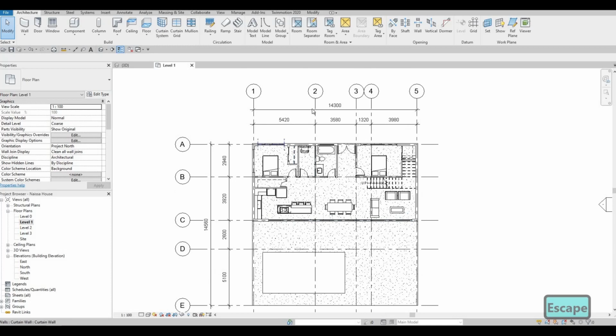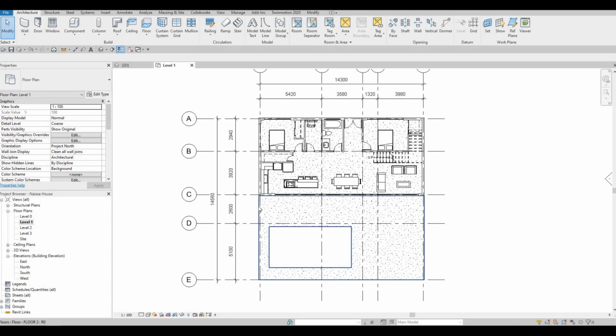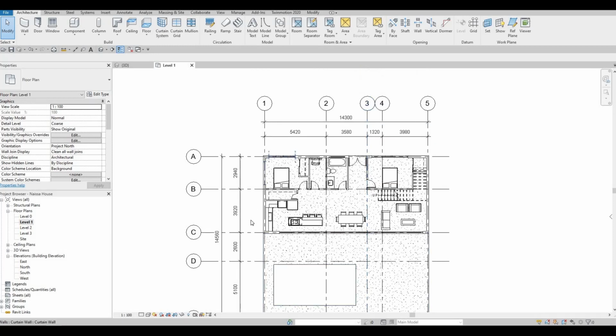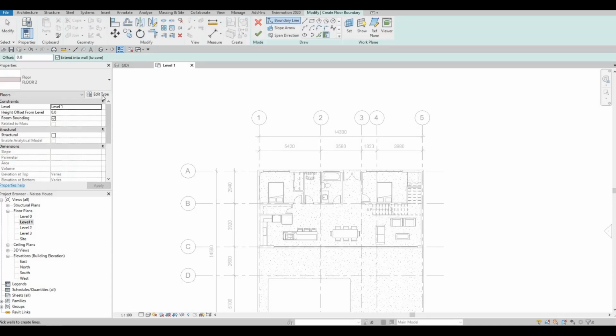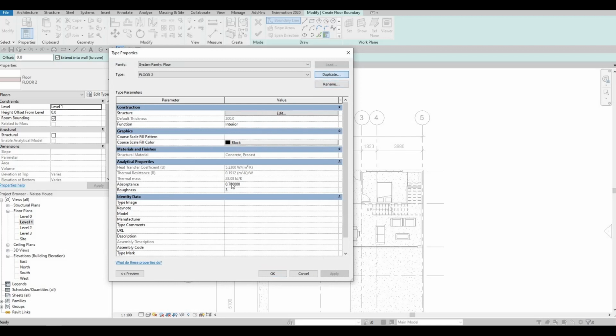And then we are also gonna create the outside here. I'm thinking if we should extend it on the side. So maybe later I'm gonna just extend it outside here. But for now, what I'm gonna do is add in this one here. So that's another floor. Edit the floor, duplicate. This will be floor number 3.